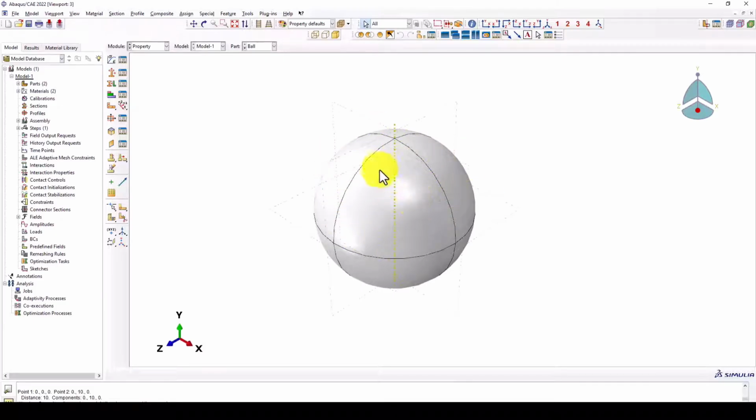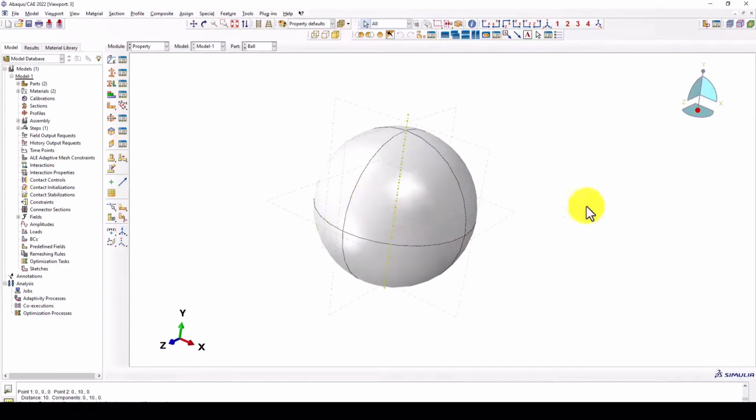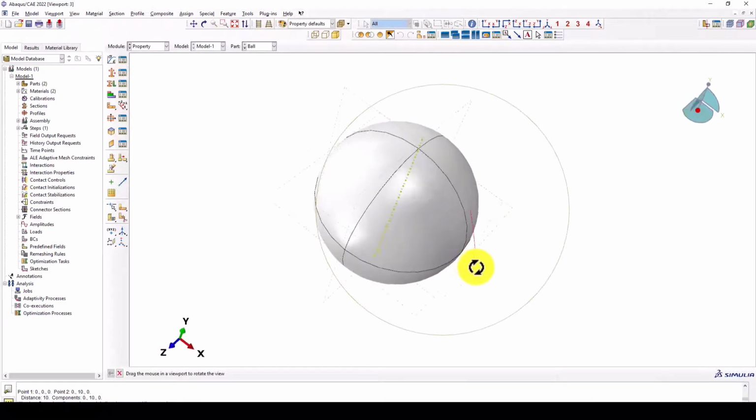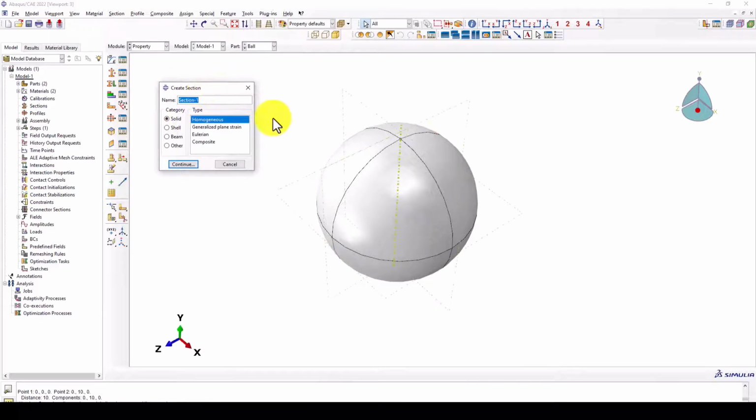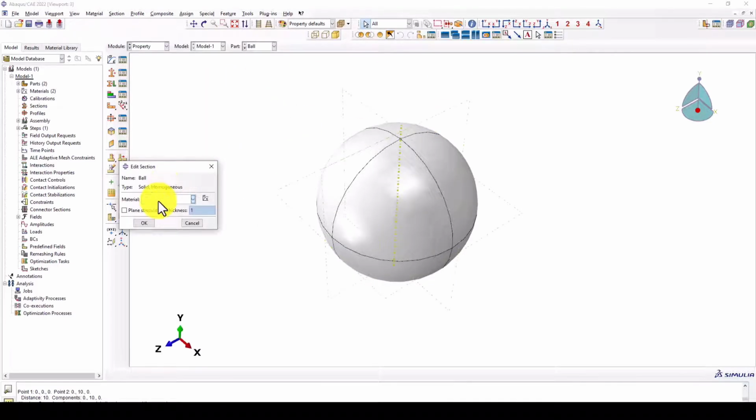The major downside that it carries is that the stable time increment can become very small. So computational efficiency at your end, or upon the hardware, becomes very important. This is where modeling choices come into the picture. That is the mesh size, element type, material density, mass scaling, and rigid body, which is very, very important.